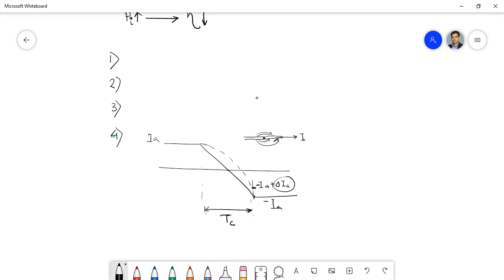Now if there is no current, and in that situation we break the circuit, there will be no arc. So that means the generation of arc and spark depends on how much current was flowing previously. Here also, how much spark will be generated due to this type of delayed commutation depends on how much delay is there.